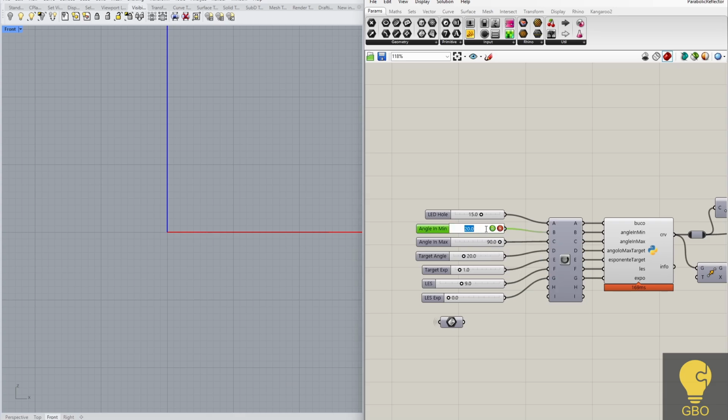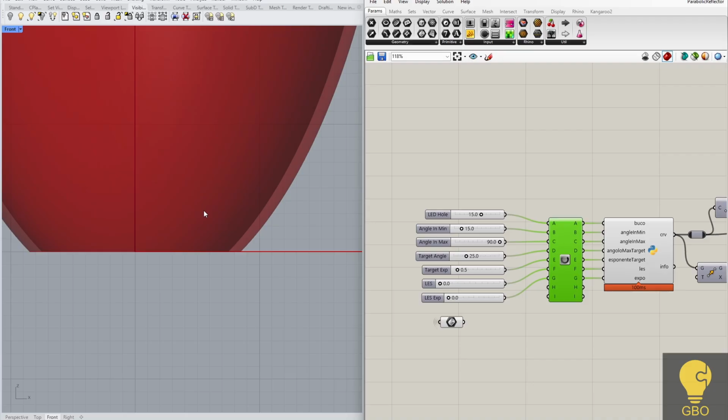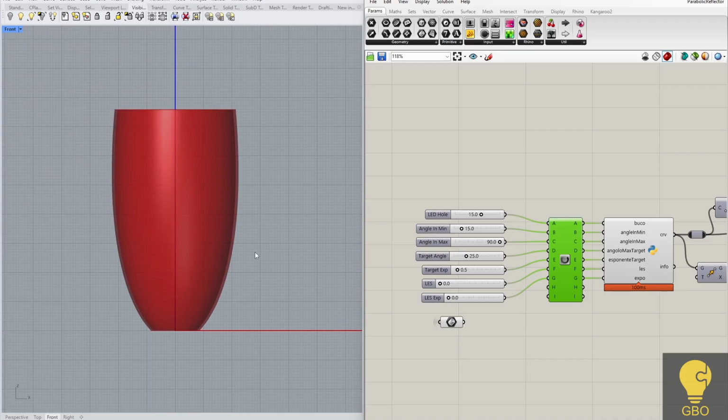So, how do we proceed in practice? Academically, every optic, lens or reflector, is designed starting from a point source. There is really no other way to start. So we take a point source, and from there we draw the base optic that gives us, at least to a first approximation, the shape that we need. Here, for example, I'm looking at a reflector computed exactly that way, starting from the origin.